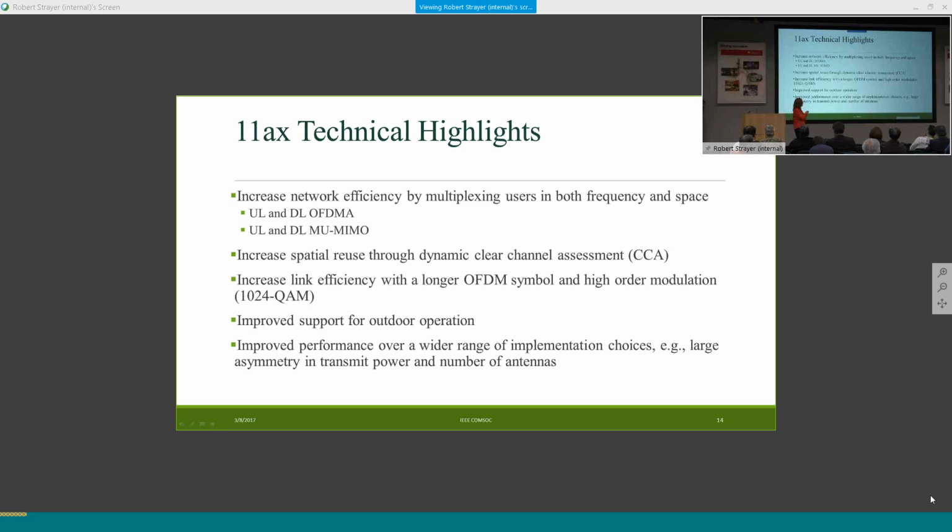But it was introduced in the uplink, and we will see that uplink has its own challenges, so that was the new effort. And the other thing is the spatial reuse. Again, Wi-Fi is listen before talk, and in fact it is very conservative. So the detection threshold is at -82 dBm.